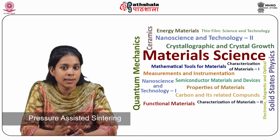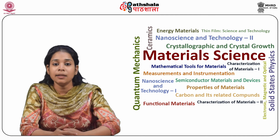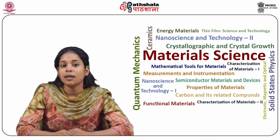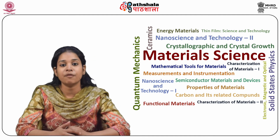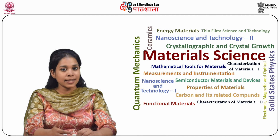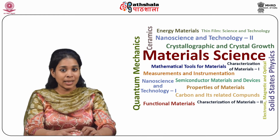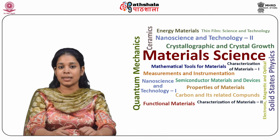So first it was pressure assisted sintering. In this, a pressure is applied during sintering, that's why it is called pressure assisted sintering, and the external pressure directly adds to the driving force, which varies as 2γ/r. The concentration of vacancies near grain boundaries is increased, and there is increased diffusion of vacancies from grain boundaries to pores, leading to increased densification. The pressure may be uniaxial or isostatic, and for these cases we have read about hot pressing or hot isostatic pressing. These pressing techniques are quite expensive and are used to sinter difficult ceramic products. They can produce some parts with nearly 100% density.